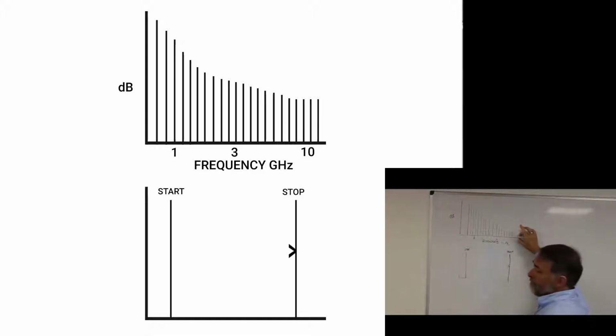The benefit of this actually is, with this one, you really haven't got much signal available at high frequency. It's really quite small, and so the dynamic range, we get into the noise floor quite quickly. So when we're making these really high frequency assessments of our network, we're not hitting it with very much signal power. But a VNA is going to hit it with the same signal power at every frequency.